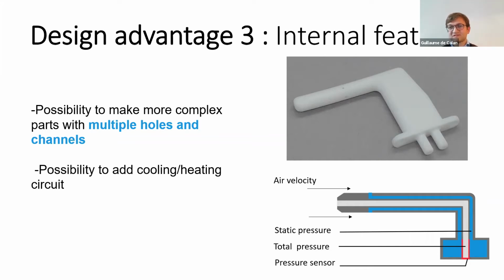It's a small part. It's quite simple to make by additive manufacturing. But if you want to do this by any other process, any other ceramic process, it is just impossible because you have these internal channels with several changing directions, which make it impossible to machine, impossible to inject or impossible to mold in any other way.